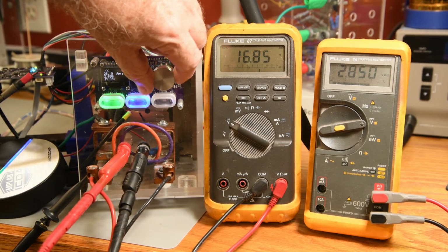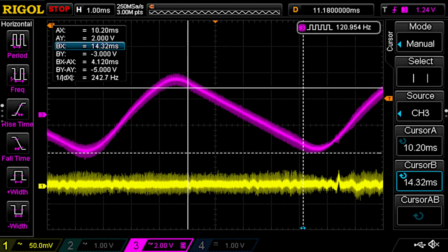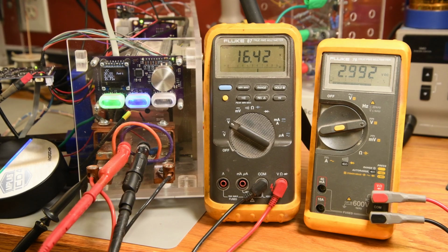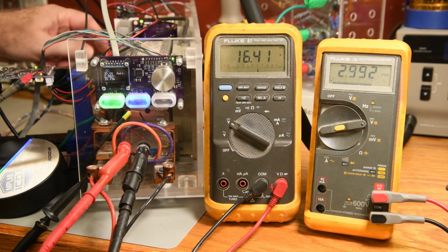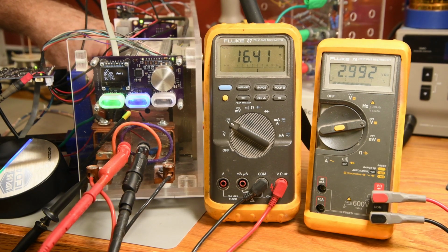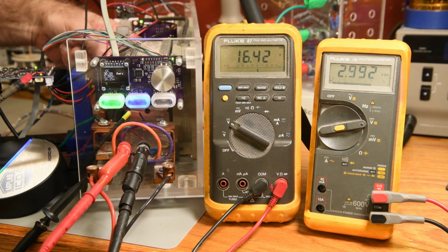I'll go up to 30 amps. That's right at 500 watts. The waveforms continue to look about the same. The 120 cycle ripple is getting up there now, close to 7 volts. It's supposed to be a 600 watt power supply, and I think it is. A lot of warm air now. I can still keep my fingers on the leads, but I don't have any temperature sensors on the power transistors yet. And I don't want to melt anything, so I'm going to stop at 30 amps.